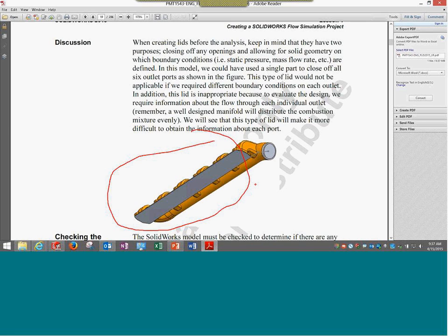But obviously, try to understand it will be a pressure, it would not be an absolute boundary condition. If it is a unit area, or even velocity for that matter, it should be okay. Here we are assuming, or this will be useful only if, the pressures are constant at all the outlets.